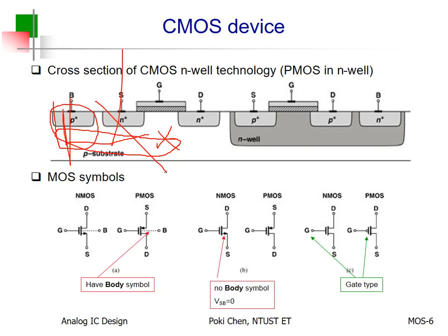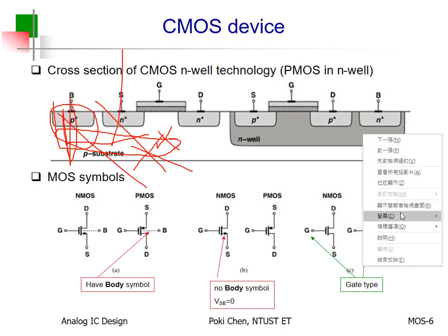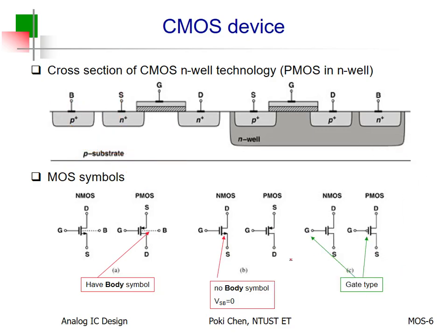So what can we do to save money? No buried layer, no such deep layer for you to connect your body voltage, body bias. Instead, the body bias is applied again beside the main part of your MOSFET, but I need to point out, as close to your main body as possible.